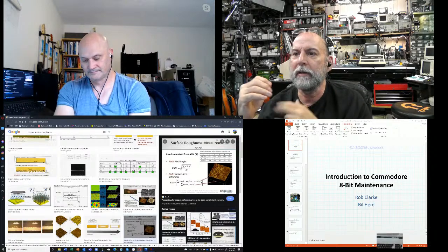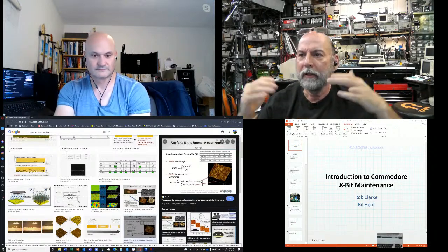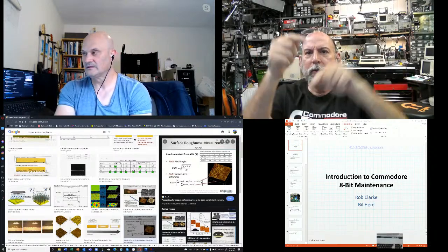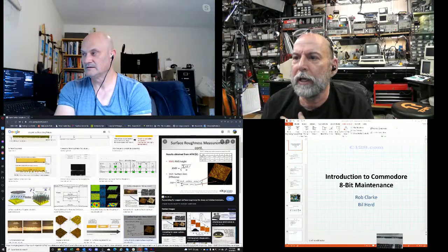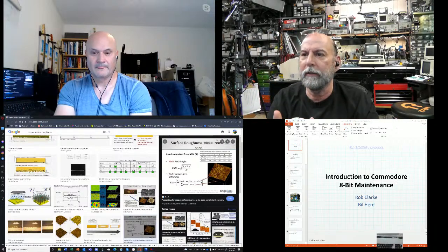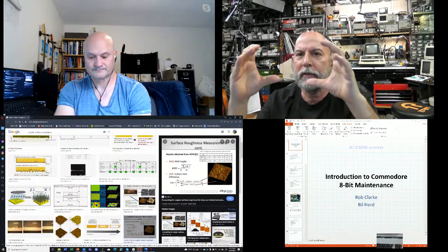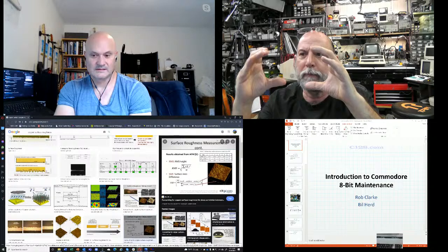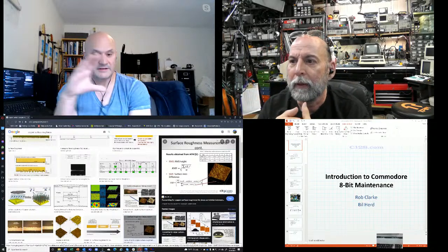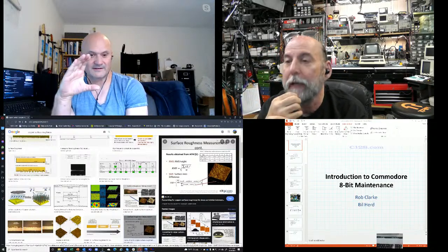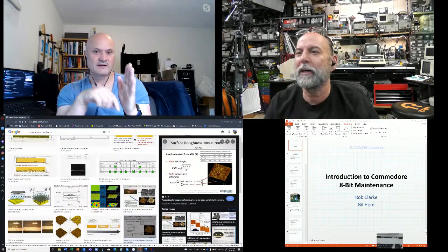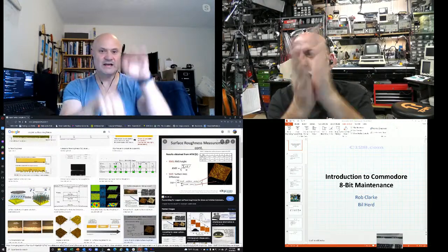But at the end of the day, we've got 2 signals in a differential, and we're detecting those edges. The energy of the edges is what helps propagate. It says, okay, that was the transition, and now we're holding that transition occurred, which keeps the openness of the eye diagram. You need to hold it as well, so not holding it sucks too, right? So you gotta get there quick and then hold it.